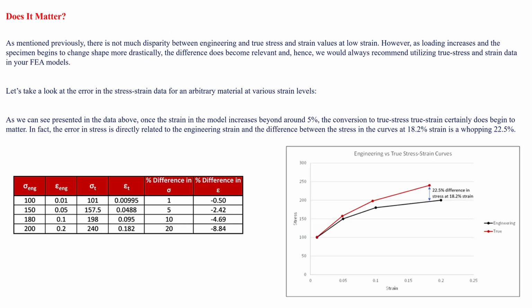So does it matter, engineering stress or true stress strain? Yes, it does matter. As we mentioned before, there is not much difference between the engineering and true stress strain for lower strain values. However, as loading increases, the specimen begins to change its shape more drastically due to Poisson's ratio.